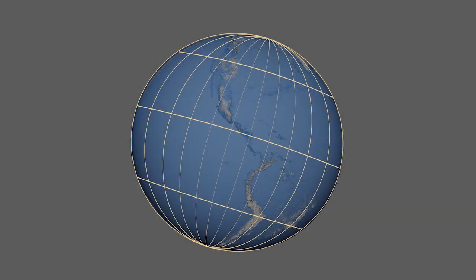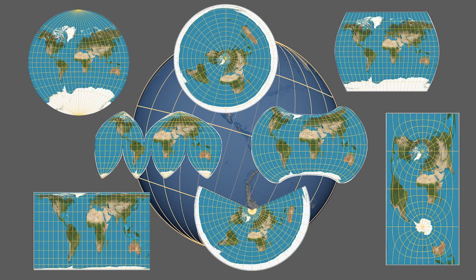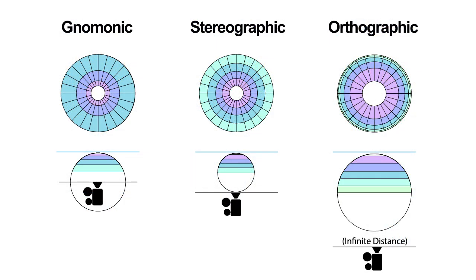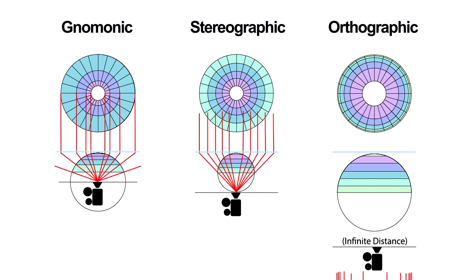Using our smooth surface, we can project a flat map. There are dozens of map projections, and all have some distortion. The area of least distortion will be the section of the two-dimensional plane touching or intersecting the globe. Each projection has its advantages. Planar projections project the surface of the globe onto a flat surface. The projection point can be gnomic, or from the center of the globe, stereographic, or orthographic.